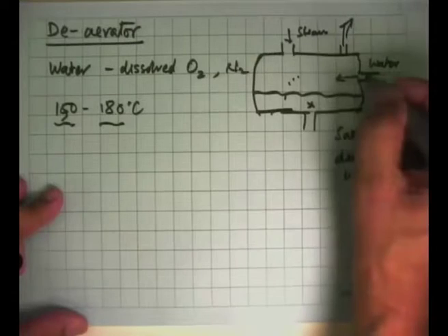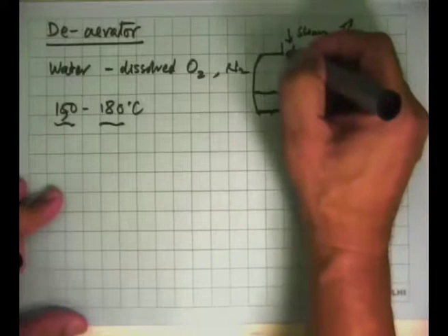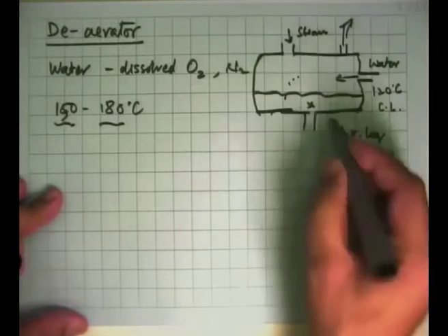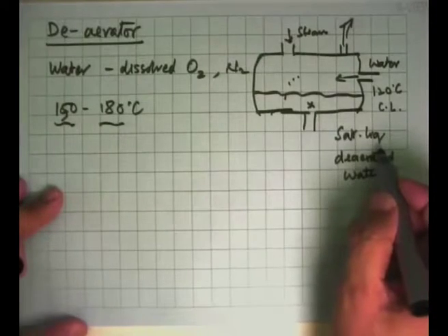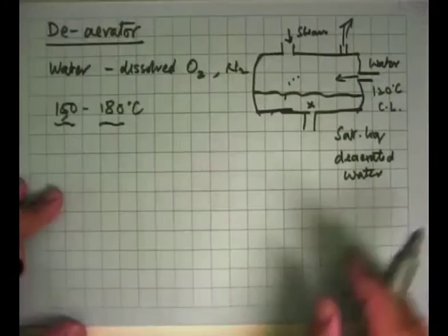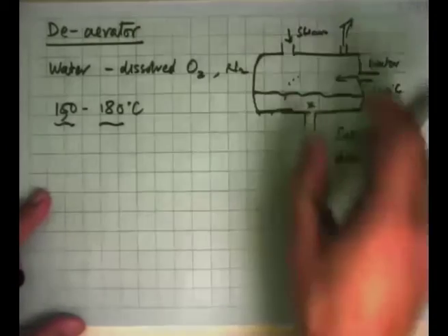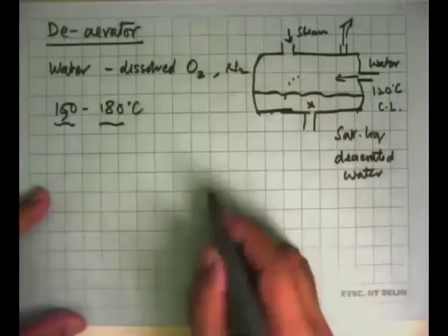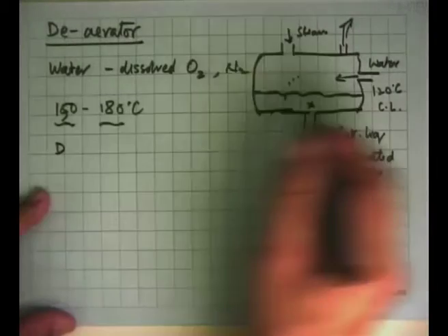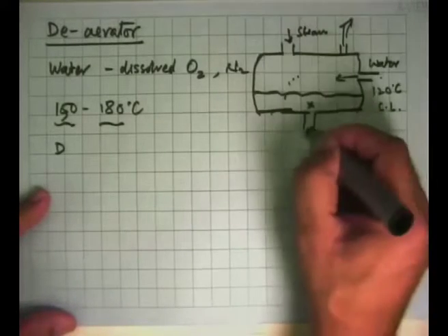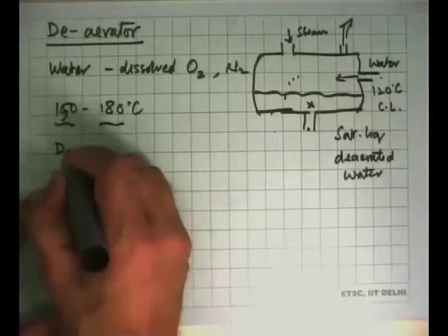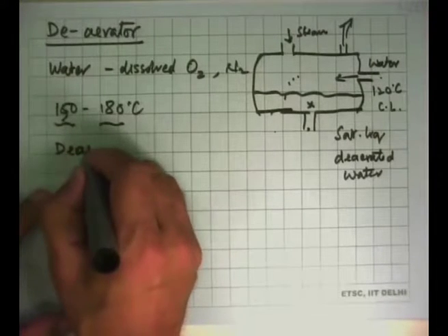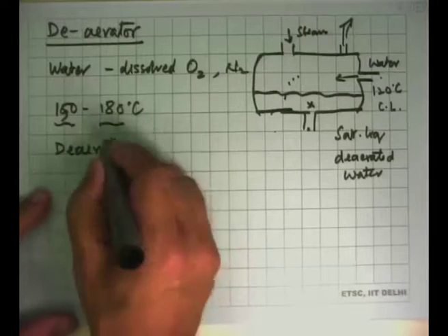So you have mixed compressed liquid with a superheated steam or dry saturated steam to produce a saturated liquid. The equations, everything will be identical to what I have just done, and the analysis of this can then proceed. In vapor power cycles, this is also called a deaerator, and it is combined with a temperature rise. Water came at 120 and it goes out at, say, 150. This is a deaerating feed water heater.